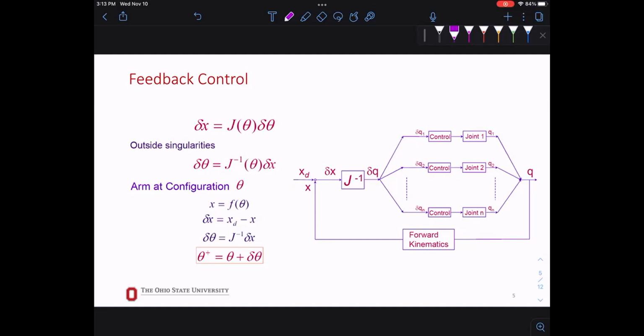You end up using a genetic algorithm, some adaptive algorithm, because there are so many joints. PID is 3 gains. Let's say you have 6 joints, that's 18 gains. You can't be doing one by one. You have to develop an intelligent method of tuning. But that's the part where you can't use the normal method of tuning a PID controller.